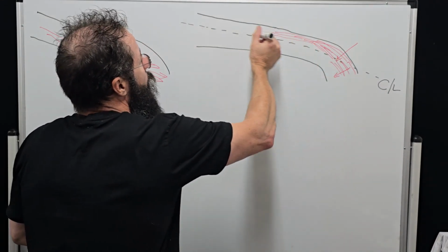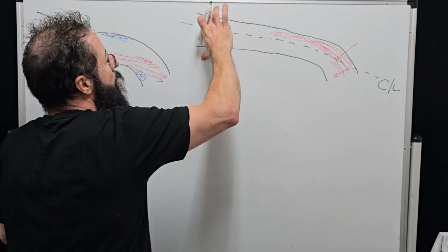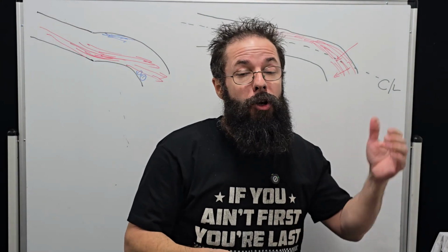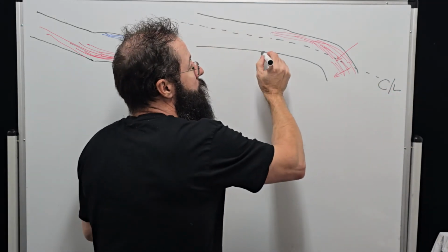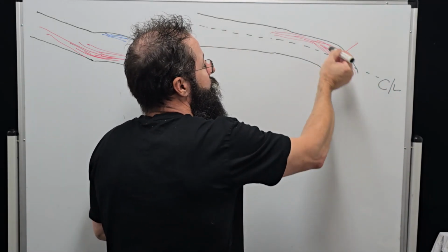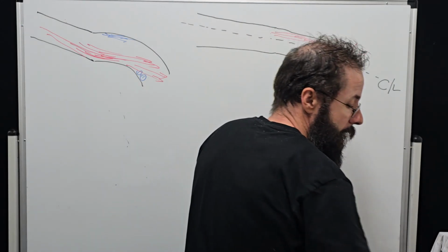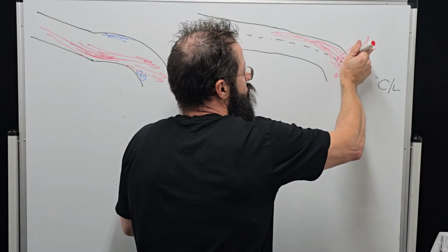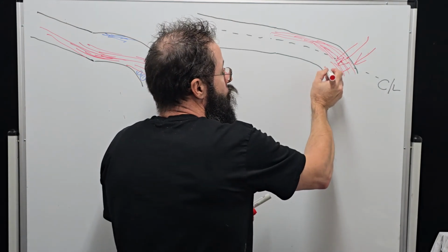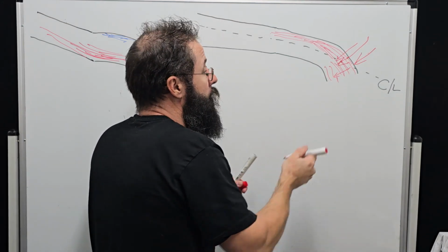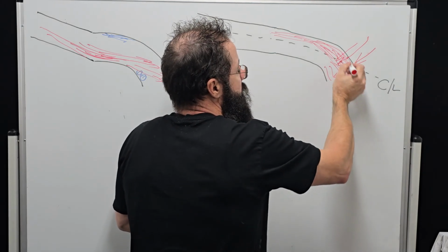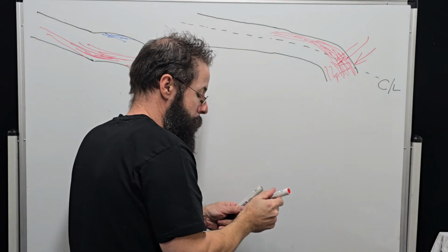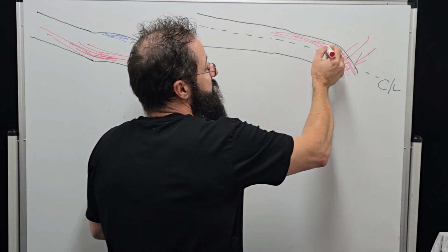So if we extend the port center line, you'll see the runner is slightly downhill. Now what this does is improve the pressure gradient across the port. So we're still going to get that pressure gradient on the far side, but what it does is it tends to push back at the short side and create more short side stability, because now all this air, and especially if we get the speed right, if we can turn that pressure front properly,